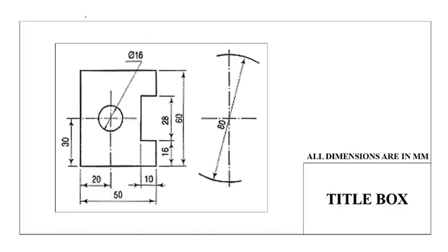Suppose this is your chart paper, this is the boundary of the chart paper, and this is the figure that you have drawn. You can see here these figures do not contain the unit. Also, the height of the dimension figure has to be between 3 mm to 5 mm.